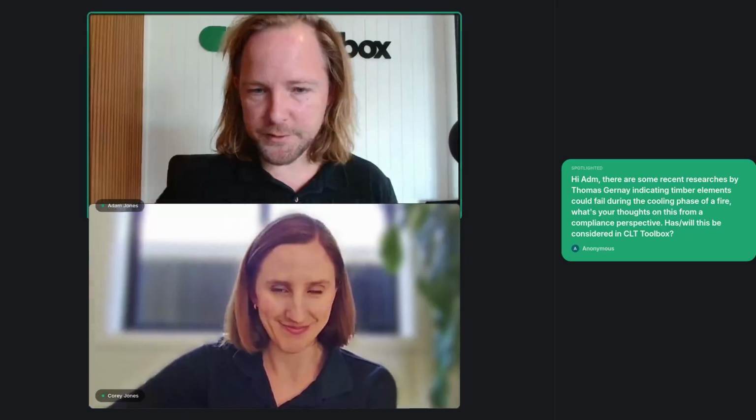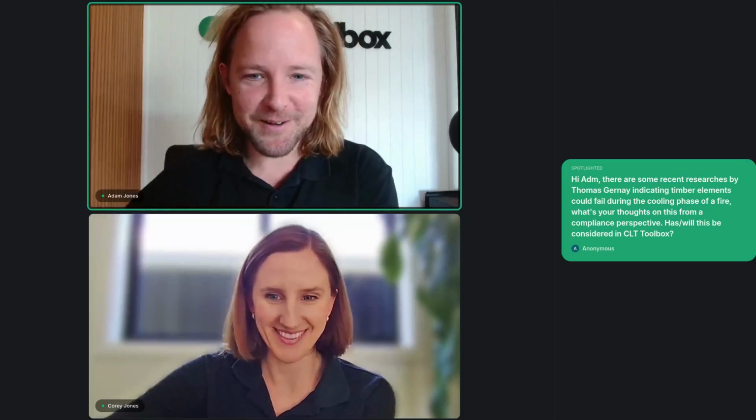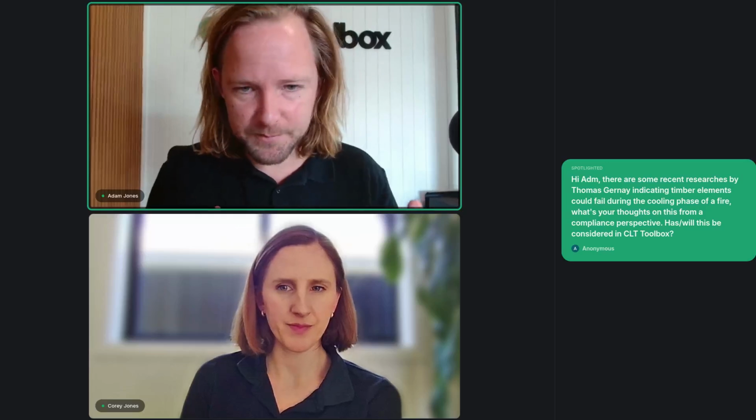That's a really good question, and I was waiting for it because there are some serious fire experts joining this webinar, so I was expecting some deeper questions. Hence, I opened the webinar by saying our green ticks are sometimes a relatively narrow scope compared to the broader range of fire engineering challenges. And as you said, during the cooling phase of a fire, elements may fail, but I'd imagine they only fail if the charring gets to a certain point where the reduced cross-section is what fails.